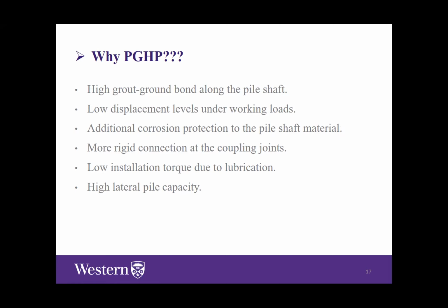The grout column provides additional corrosion protection to the pile shaft material. So if you are expecting to install your helical pile in corrosive soil, adding this grout column provides a kind of protection against corrosion. The grouted shaft also makes the connection at the coupling joint more rigid.